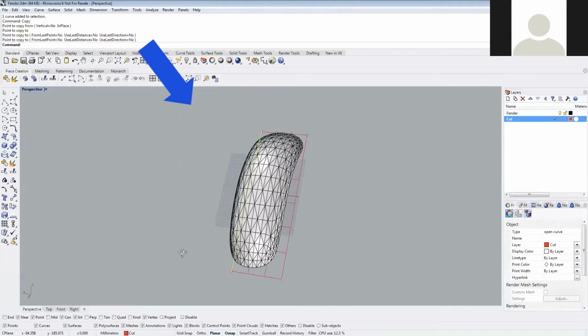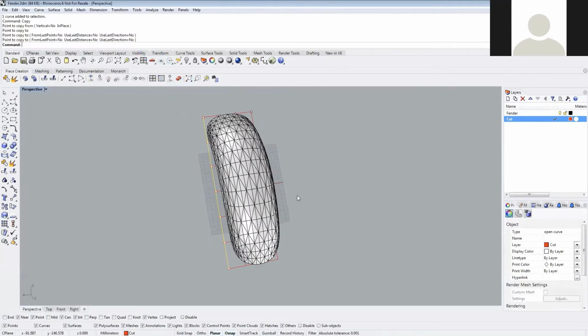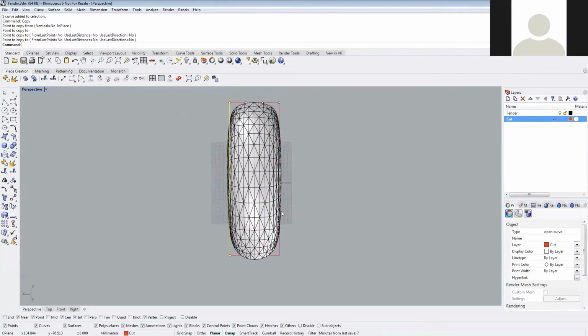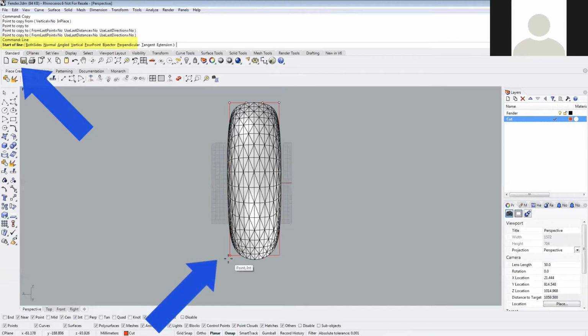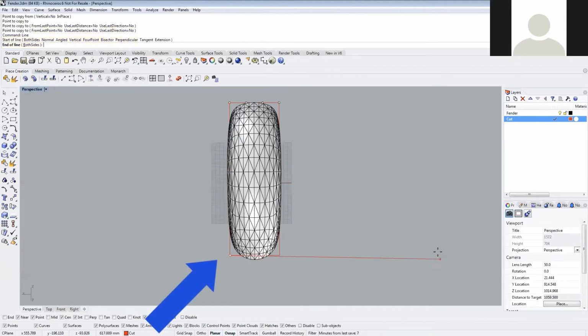Lastly, we want to split these different layers, some of them so they're perfectly vertical. We want to split another layer so it's perfectly horizontal. And then for the third layer, we're going to split it at a 45-degree angle. So what I'm going to do is create a third curve. We're just going to use the line command. And I'm just going to create the curve and drag it out here.